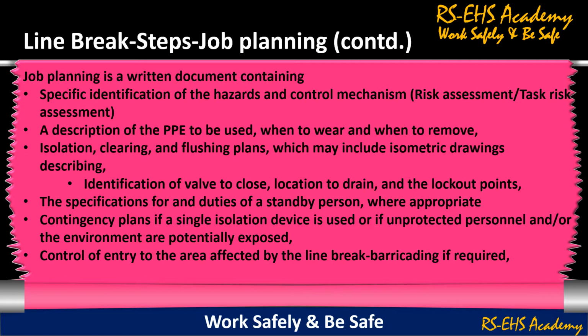points, the specifications for and duties of a standby person where appropriate, contingency plans if a single isolation device is used or if unprotected personnel and or the environment are potentially exposed, control of entry to the area affected by the line break, barricading if required.